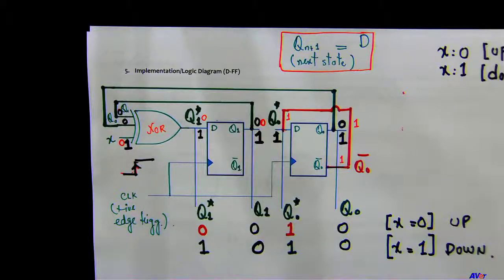If you look at the clock right here, you just have one clock. We got one clock, and that is fed into both flip-flops. So this is synchronous, correct? It's not asynchronous. It's not like the output of one flip-flop is connected to the clock of the next. So you see those changes in the counter at the same time. So it's a lot faster. That was example 1.